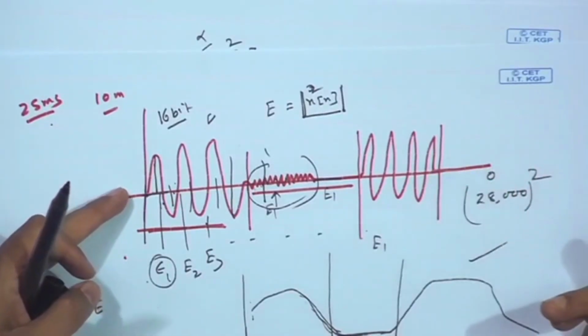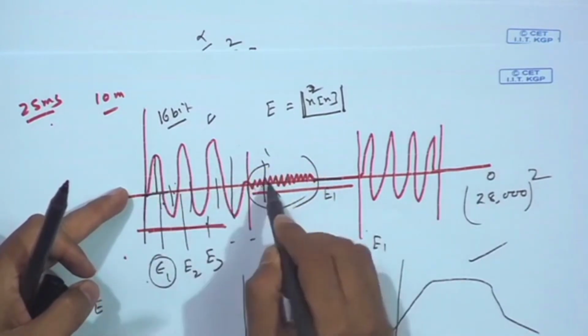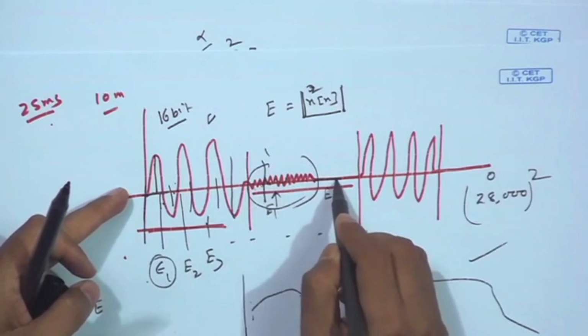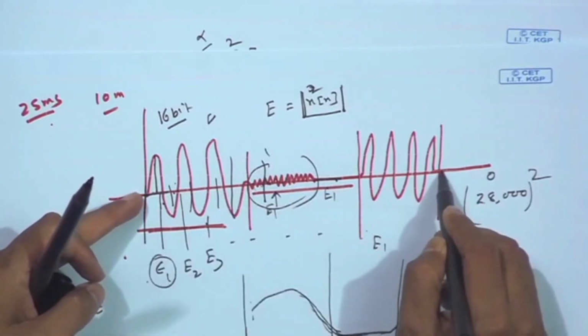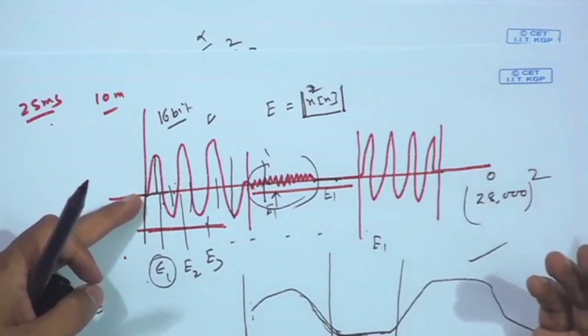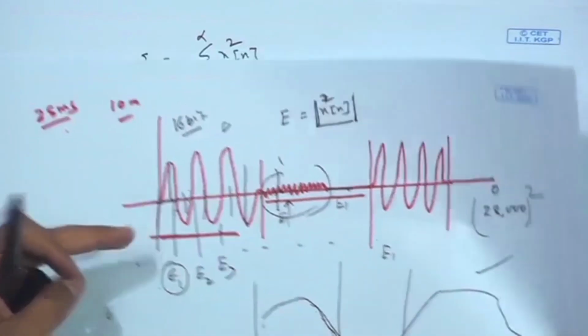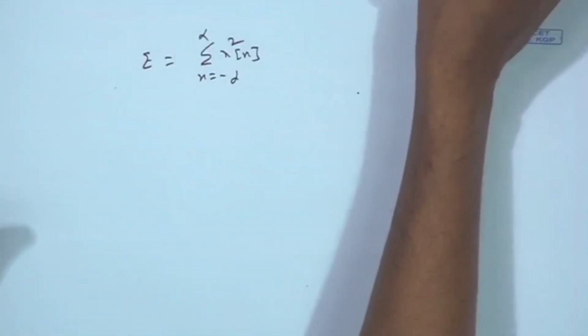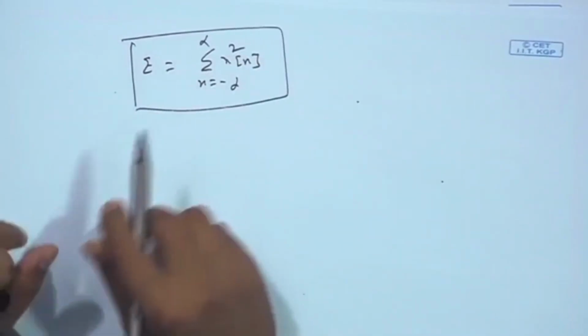I want to find out voiced signal, unvoiced signal, silence. If I take the whole signal at a time, I get one energy value of that speech signal, but can I infer any information from that energy value? No. So, there is no use if I use the whole signal at a time.